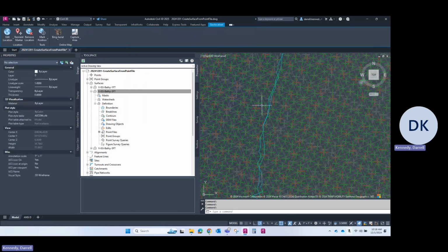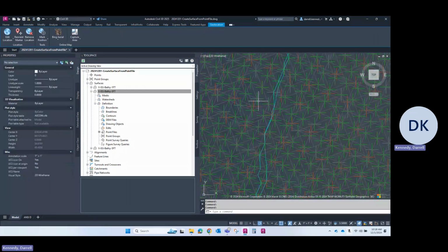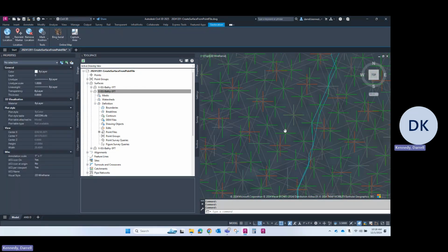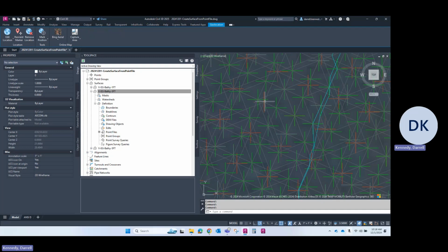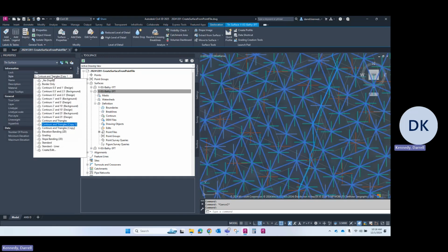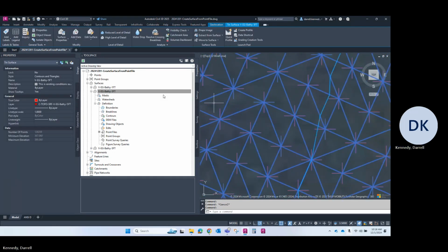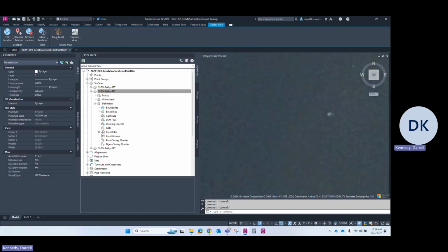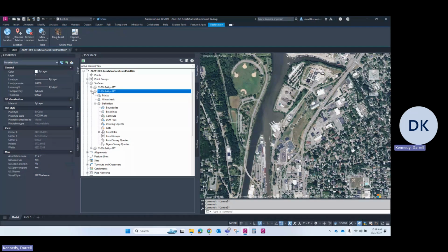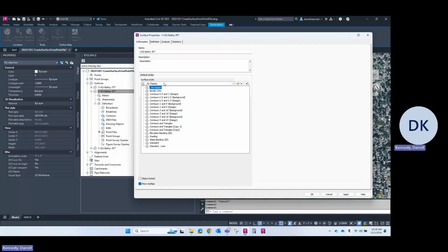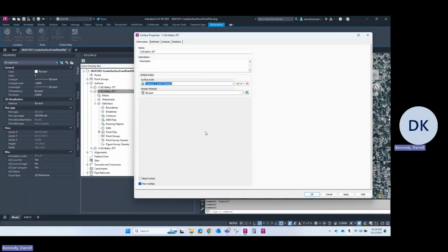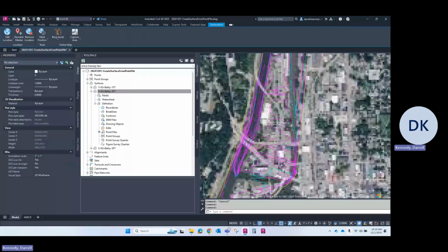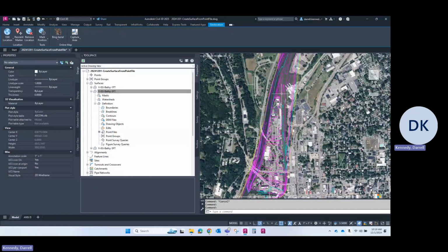It did. Okay. So you can see that the 3 foot grid is a much tighter tolerance than the 5 foot grid. Here's the 5 foot spacing, and then there are many points of the 3 foot grid within there. Okay, we'll turn both of these off. I'm going to turn this one off, no display. This one off, no display. And turn the 3 foot back on, just to show you that we have not yet processed this or set the maximum triangle length. So we still have this issue.